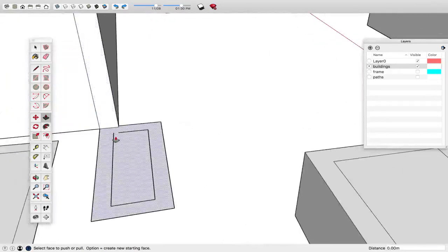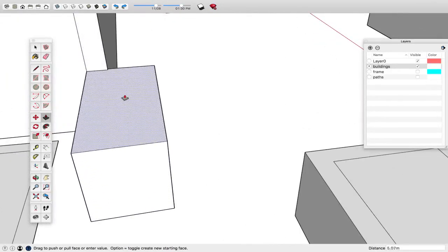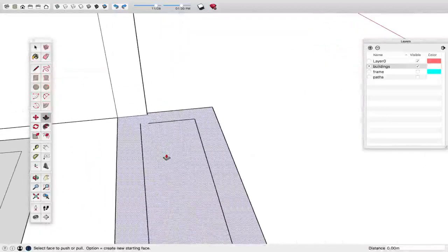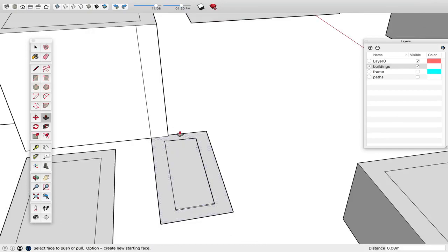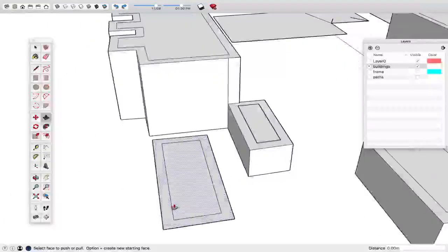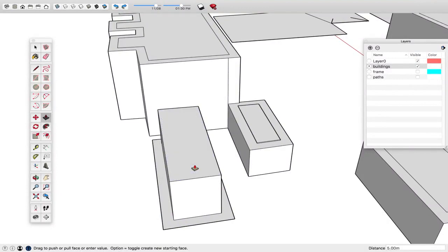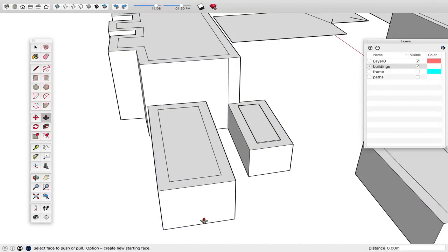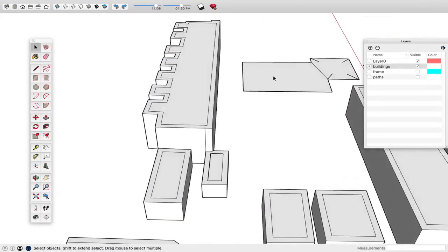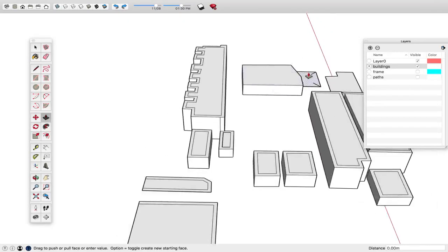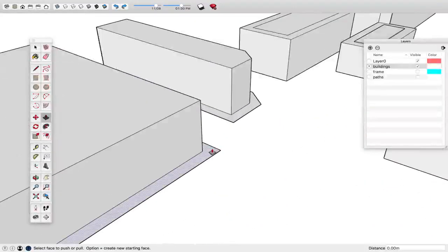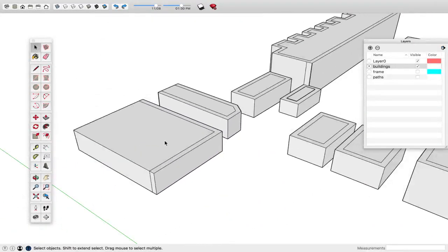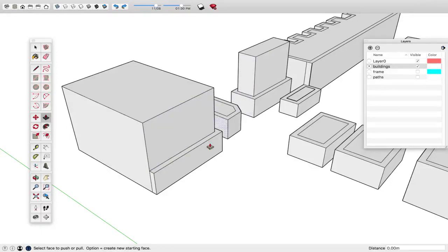See that one there? It has that little gap there. So if I move it, it's just going to be like that. If you wanted to fix it, get the line tool. Also, if I go, say, 5 meters, if I double click that, 1, 2, it's also going to make it 5. P, double click, do 5, 5, 5. So if you've got many things the same size, you can just double click them. Set it once. If I then set this to 10, if I double click this, 10.